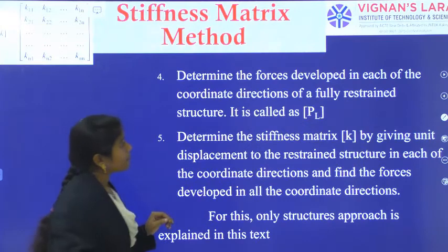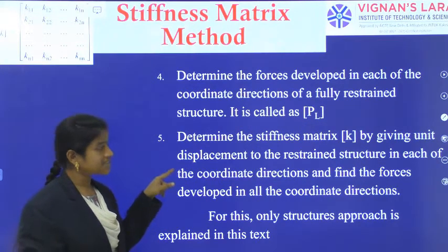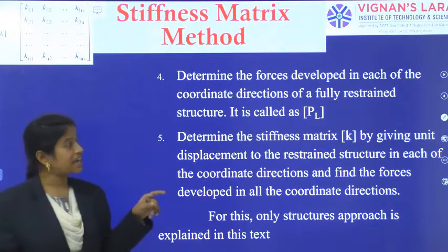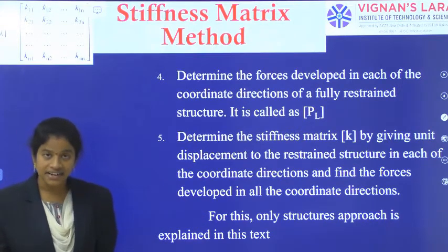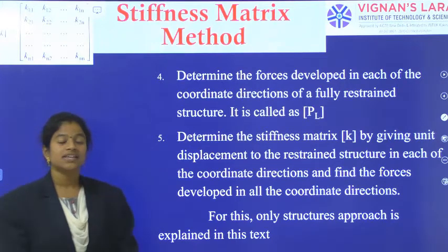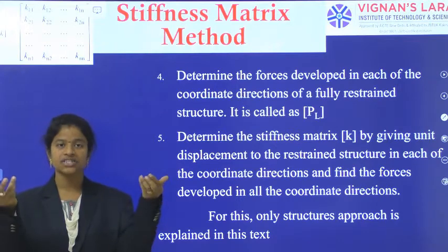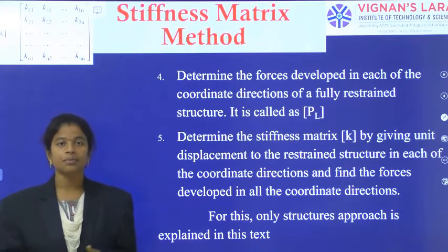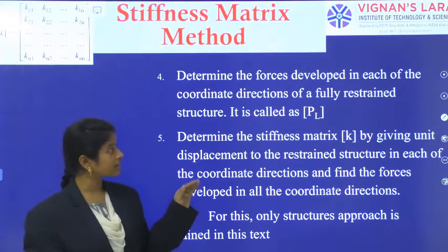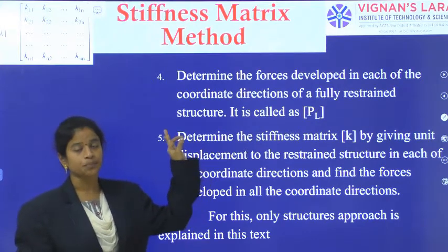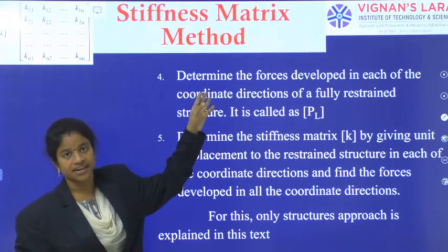And then determine the forces developed in each of the coordinates in the fully restrained structure, which is called PL, the load developed for the restrained structure. Loads are the forces generated. So in the case of a fixed beam, what are the corresponding support moments? That support moment matrix is PL, the load or force generated for the fully restrained structure.